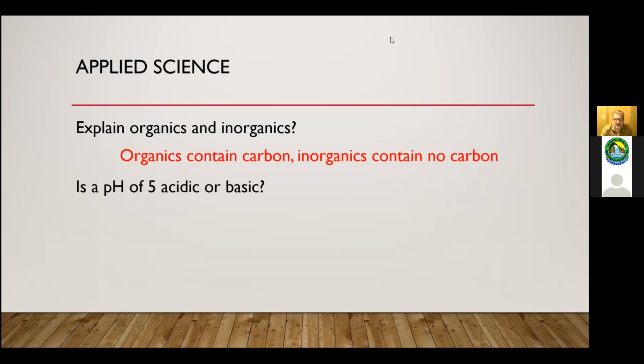Is a pH of 5 acidic or basic? Acidic. Correct. So if it's acidic, you're going to get corrosion. Also detrimental to your bacteria. If a low pH situation exists for a long period of time, bacteria in your bioreactors or mixed liquor tanks or RBCs or anywhere your microorganisms are going to suffer.